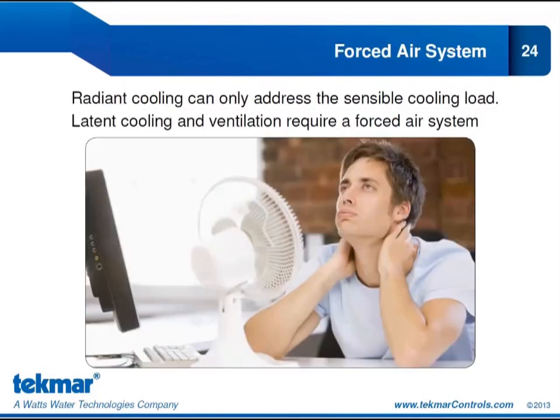However, radiant cooling can only address the sensible cooling load. We cannot remove humidity with a chilled floor. Latent cooling and ventilation require a forced air system. And in a geothermal system, latent cooling is almost always provided by chilled water fan coils. And for that, we need the coldest water temperature available, typically no colder than 45 degrees Fahrenheit. When we get lower than that, then we really do start compromising our heat pump efficiency.